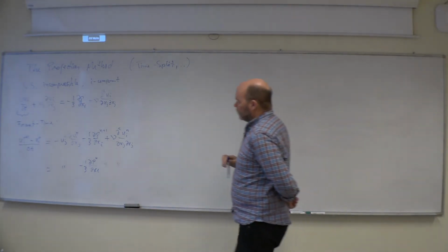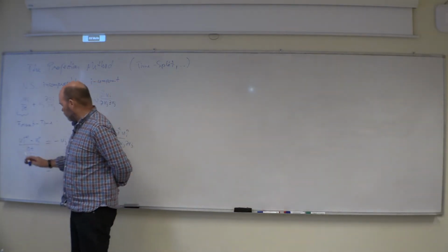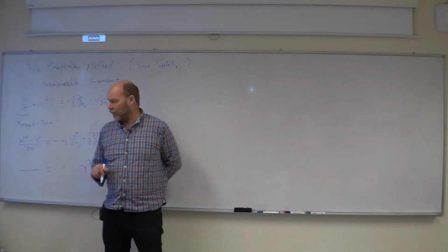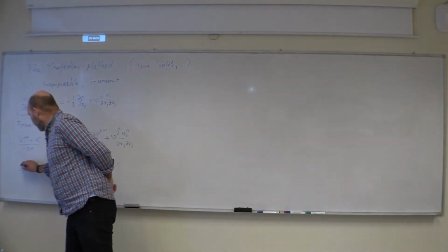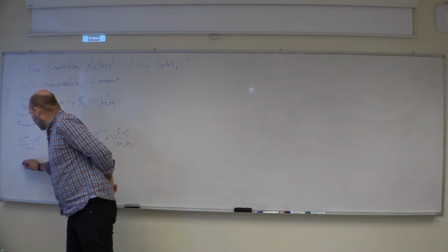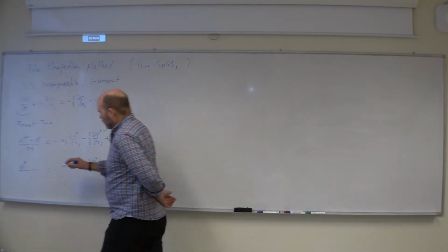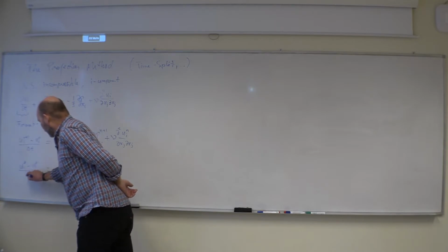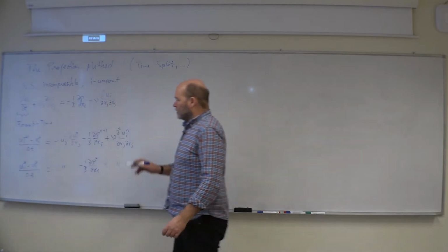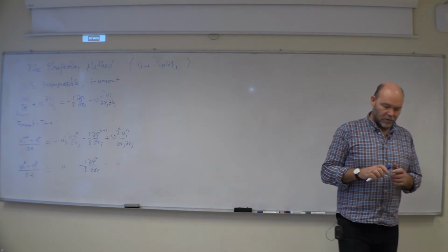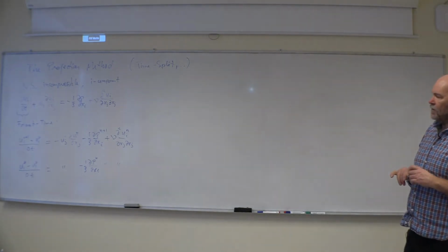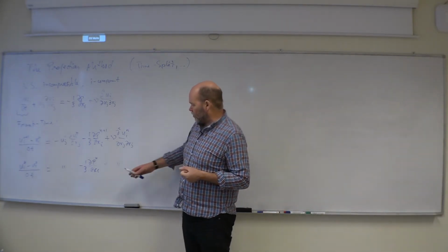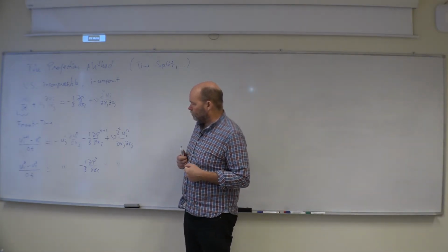Then I have to admit I can't find the correct new velocity. I find what's called a tentative velocity field. I find a ui star, and then minus the old one, because I use the old pressure. So the ui star there, the tentative velocity field, is very easy to find. That's the explicit version of my equation.